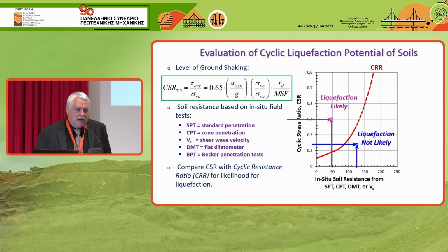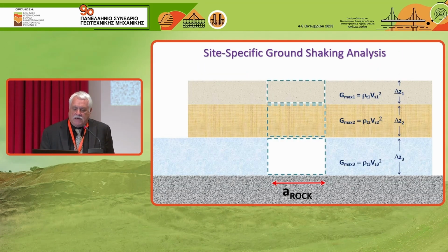liquefaction's not likely. That's how it was handed out to us by Harry Seed some years ago, and people have used it. It was originally done on relative density on lab samples, but you can measure or infer the relative density from SPT, CPT, DMT, shear wave velocity.